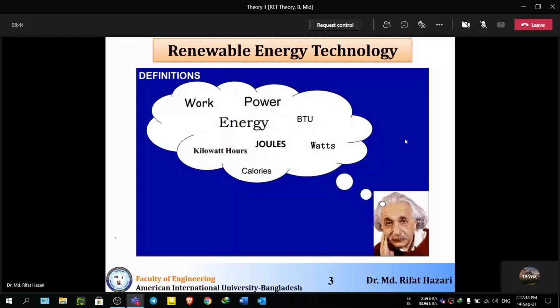Maybe the cooling capacity is 24,000 BTU, maybe 18,000 BTU, and maybe 12,000 BTU. So 12,000 BTU is considered as 1 ton, and if I'm not wrong, 18,000 BTU is considered as 1.5 ton, and 24,000 BTU is considered as 2 ton. Is it clear to you? Ton is for general people, but when you buy an AC, if you look at the catalogs or manuals, it's written not in ton but in BTU. Ton is for the mass people, but professionals always think in the BTU unit.